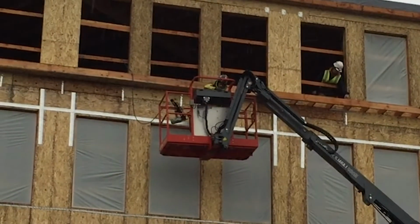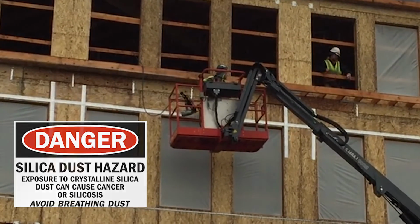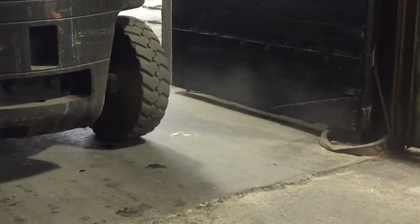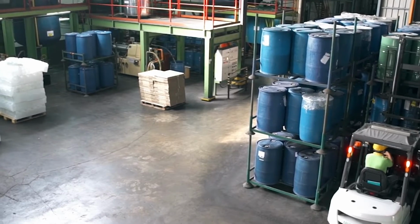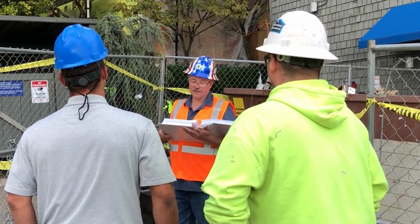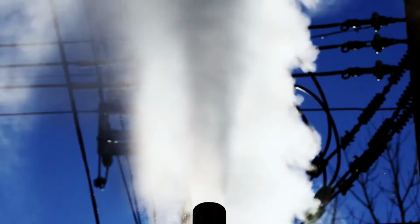The work area must be free from other hazards, such as dangerous atmospheres or falling objects. Hazardous locations, with flammable or explosive atmospheres, require specially rated aerial lifts. In addition, employees need work procedures, personal protective equipment, and training. Do not enter hazardous locations unless you have been trained and authorized by the employer.